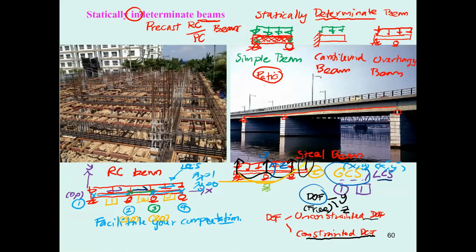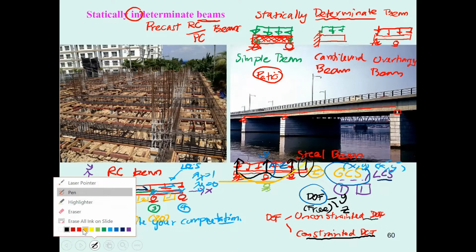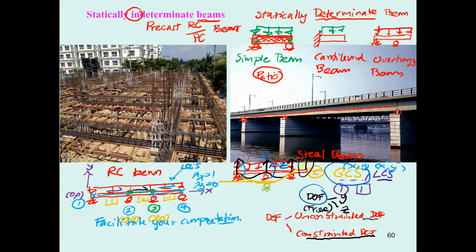So the y direction is going to be these 4 of them. And then you must have the slope of this one, which you may have as an unconstrained degree of freedom, because the slope can change when the load changes, when the settlement of the structure changes.